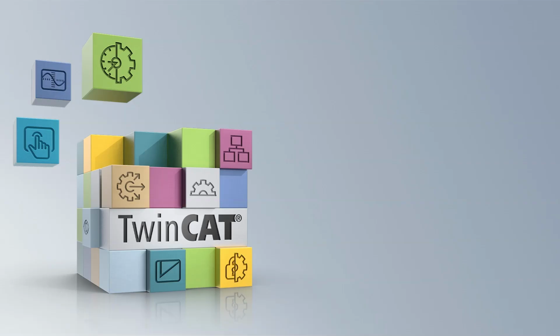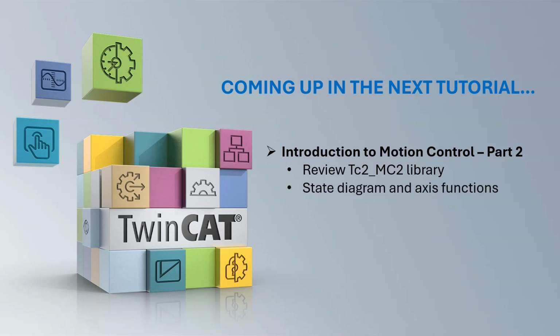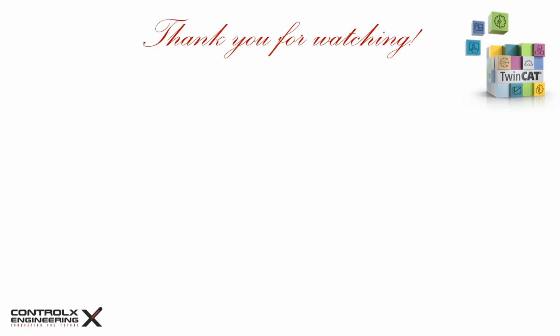Thank you, Andrew. Coming up in part 2 of this tutorial, we will review the software components available in TwinCAT, particularly the motion control library called TC2MC2. We'll look at the state diagram and also review some of the important axis control functions. Later, we'll start a new PLC project, incorporate the TC2MC2 library, and explore its various functions and function blocks. Finally, all the axis movements that Andrew performed manually today from the Axis Online tab, we'll control them from the PLC using all the available axis control function blocks.